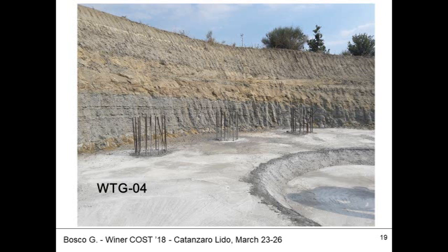What you can maintain probably is grain size composition, which is not very usable. The point is that probably we don't even keep undisturbed water content, which is very low in this material, and it is responsible for this high strength of the clay material. Designing piles in this condition is, I would say, not very easy, because we don't know the pore pressure.